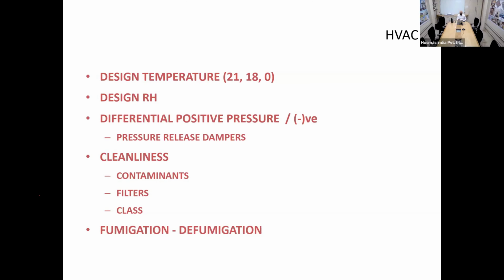So I think this very big challenge that we as engineers and planners face, that we need to plan for 16-degree, which is both capex intensive and opex intensive, is no longer going to be a criteria in the times to come. But one important element that I wanted to share is that we might be located in an area where the temperatures go sub-zero or zero. So in that case, we need to provide for heating, not so much for cooling. Something that we need to bear in mind when we are planning the HVAC. It's not always about cooling. Depending on the ambient conditions, you might be looking at the necessity and the need for heating as well. So air conditioning is about both heating and cooling.